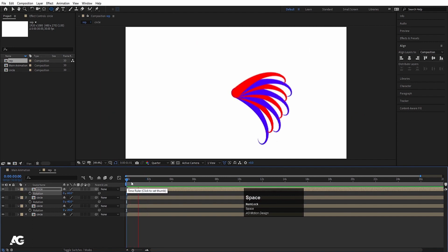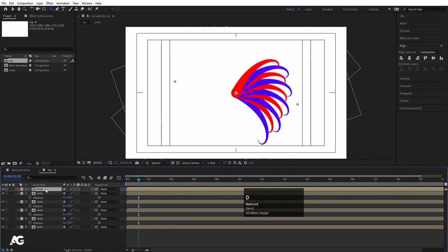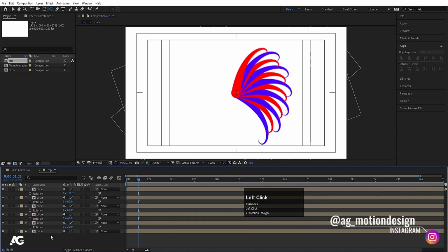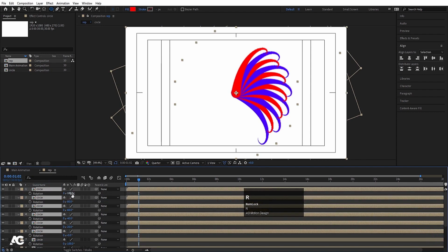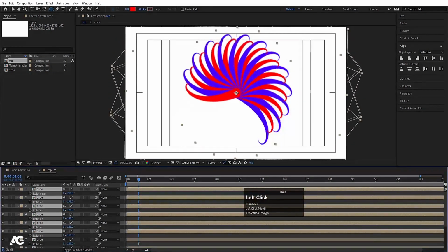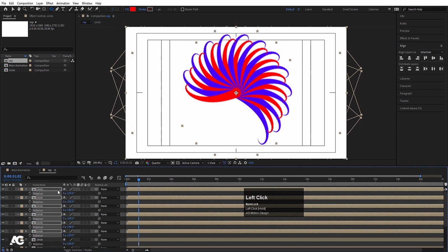Let's see how it looks. It will look like that. I'll hit Ctrl D, R, let's make it -80. Hit Ctrl D, R, let's make it -100. Now I'll select all of them. I'll hit Ctrl D, I'll drag it at the top, I'll press R for all of them, and I'll manually rotate it from here until I'm getting something like this.